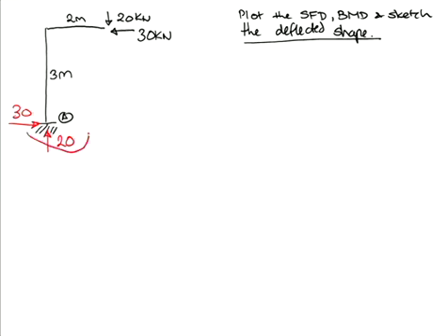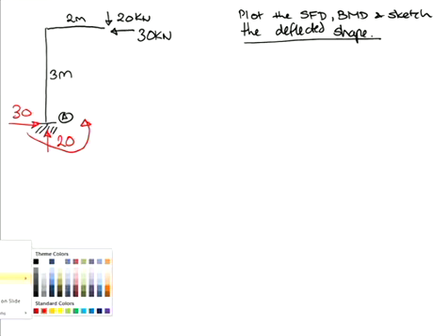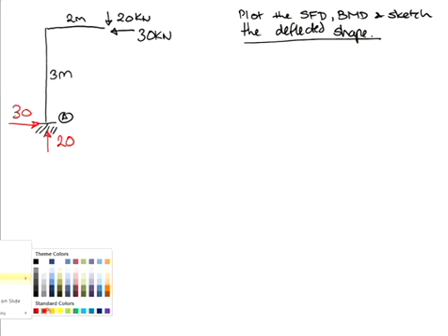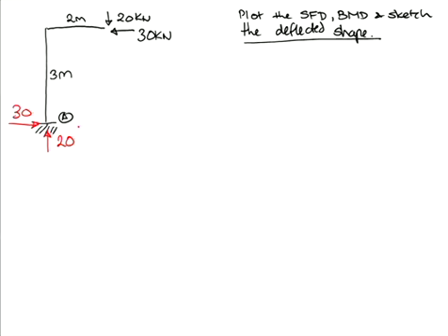And when we do take moments, it's a very wonky moment, but that moment as drawn in there, I've actually drawn it the wrong way because in actual fact it is going the other way. My bending moment, which you can work out yourself, I'll give it a positive value and draw it in the direction it's acting in, is 50 going clockwise.